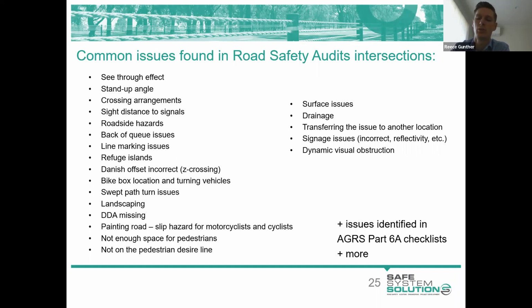What typically results is an island that's so small that it struggles to adequately shelter signal hardware as well as pedestrians. It increases the risk of pedestrians being struck at that location because they're all standing on this small island with traffic going past them in all directions. That's something I find is a common issue in Melbourne. But there are some good ones there that do come up quite often.